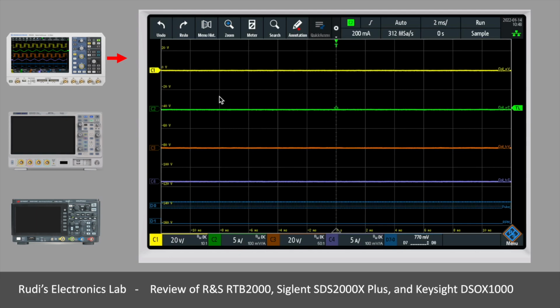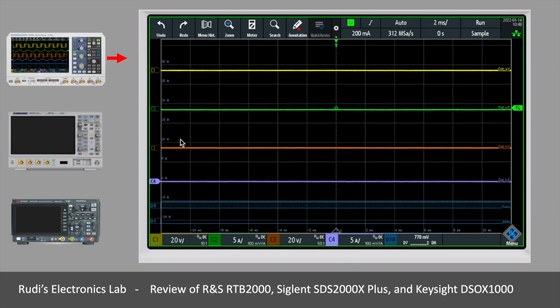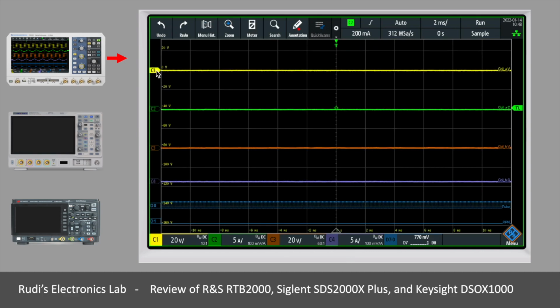So quickly, what do we see here? We see all the 4 channels and the digital channels that we've pre-configured. We see the grid here, and the grid is showing us basically the value for the grid. And since I turned grid tracking on, we would actually see that if I move to a different channel, the grid moves with it, and also here basically the settings adapt, as you can see here, to the particular channel that I have selected.